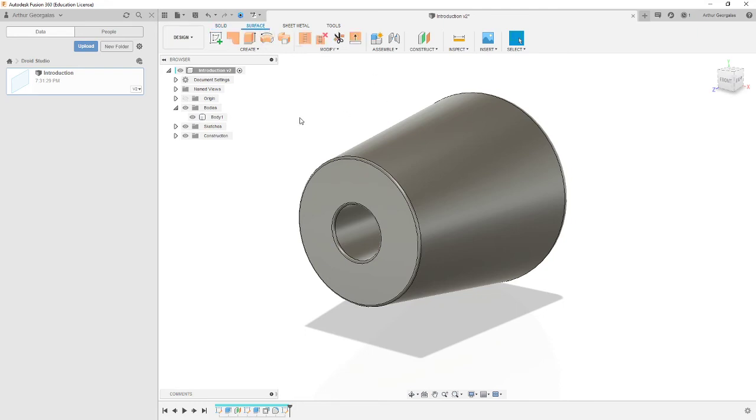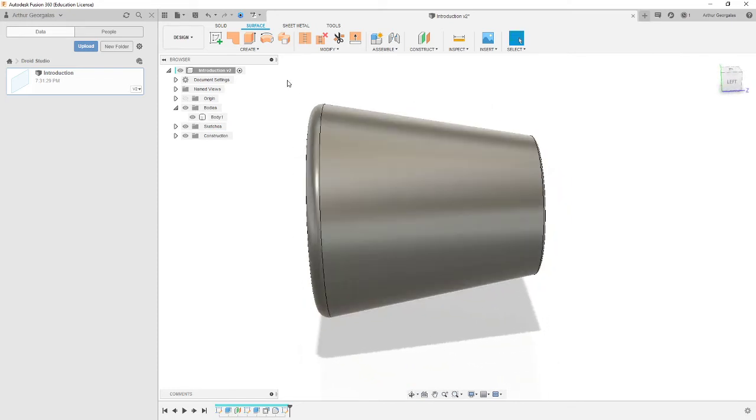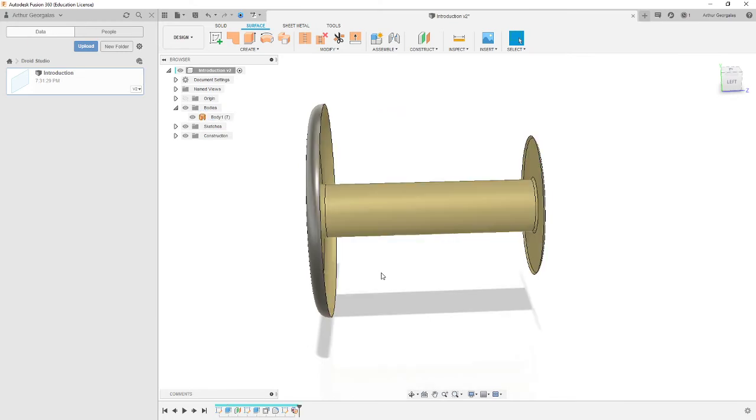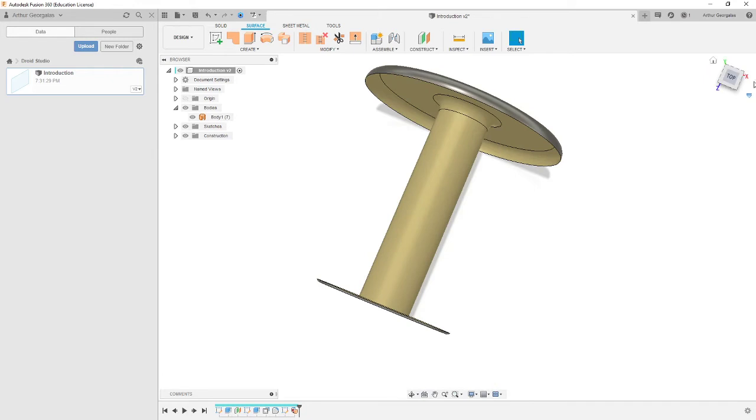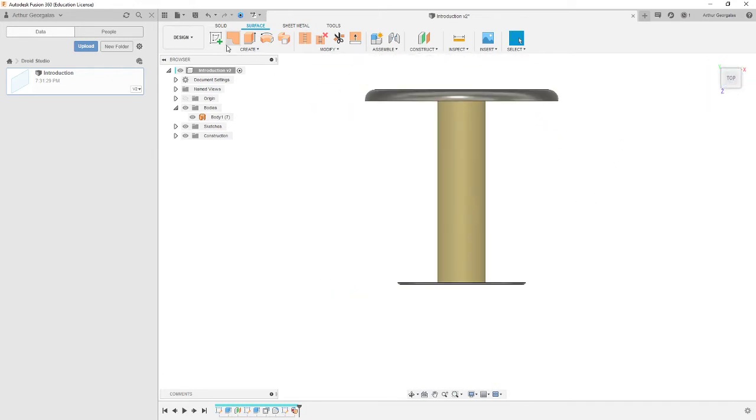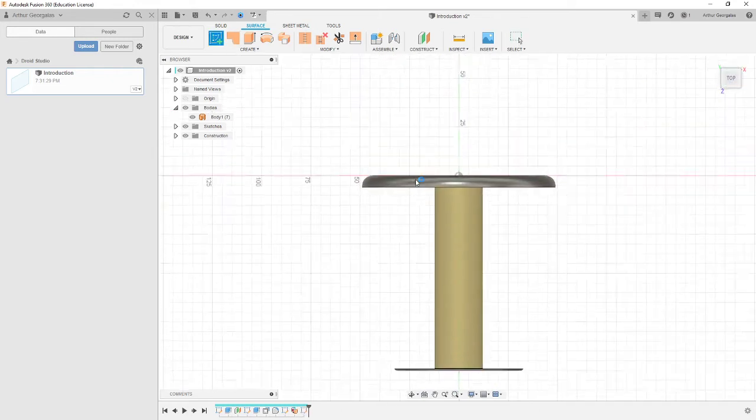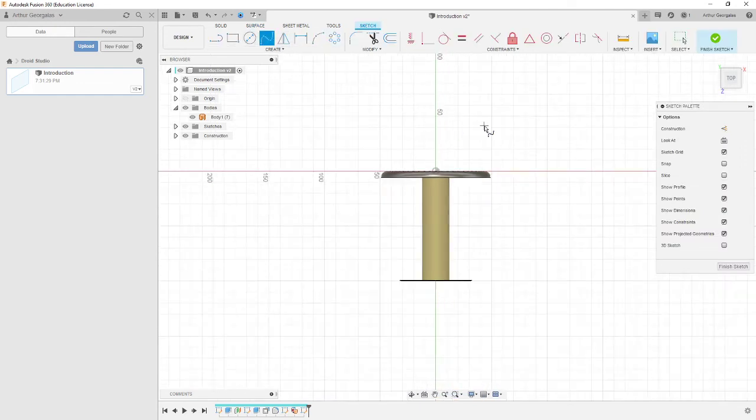Surfacing is much the same, except it has some really good options for actually trimming, but sometimes they go a bit wonky. That's kind of nothing new anyway. Alright, so I clicked that face and deleted it. Let's have a look at just doing a basic trim of a surface. So we need a sketch. We can create a fit point spline. Splines in Fusion tend to look a bit better and behave a bit better than the ones in SolidWorks, which go a bit crazy easily, although adjusting the edges can be not as fun.